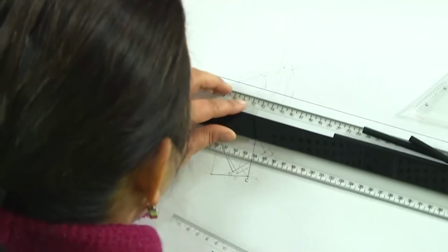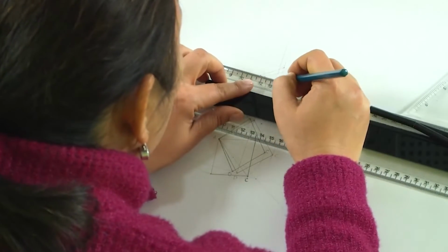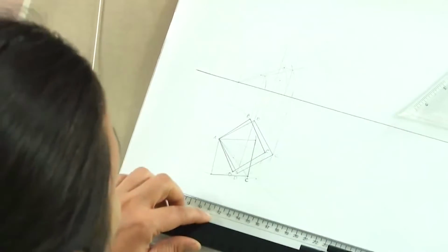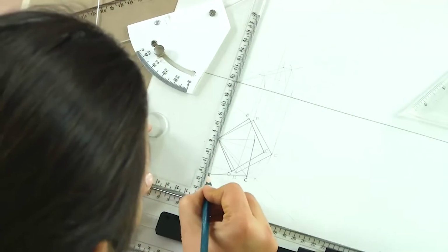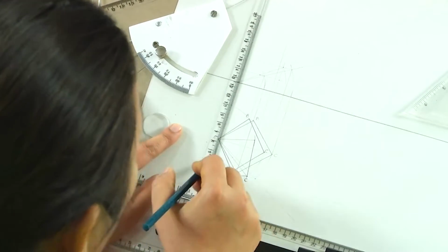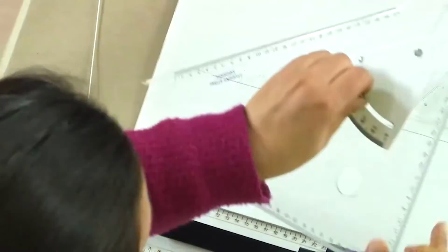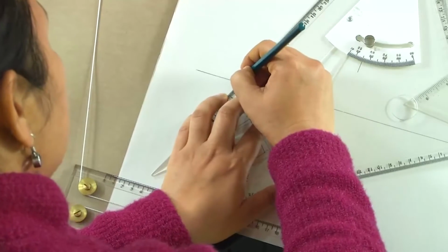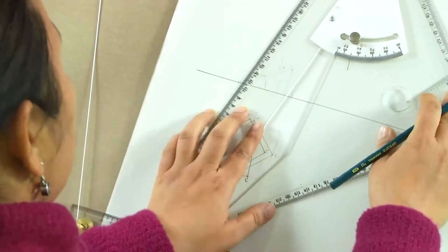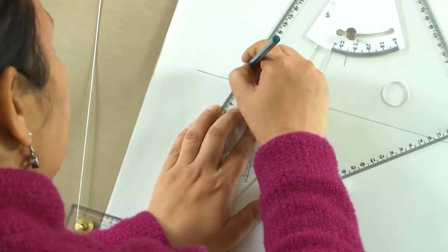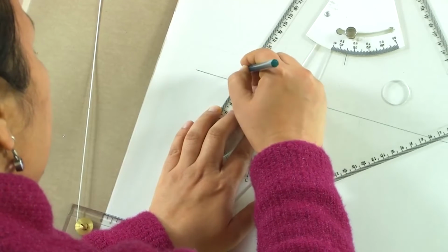And now if we project the B and D back onto the vertical plane, so we have B, and horizontally this B will come here, and then we take the projection of this point D back, which is here. So what we have finally is a very deformed shape which is seen in our vertical plane.